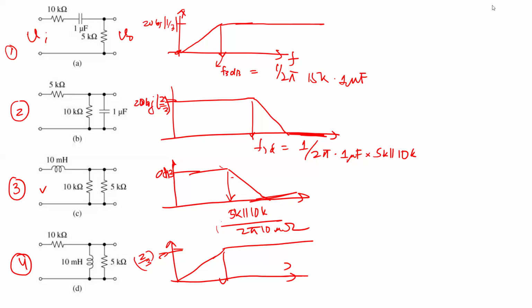If you want to go to microhenries, then you buy those elements which look like resistors, but they are wire wound. Okay. So this is just showing that you can use an inductor to do a low pass filter. For example, this one, you can see it's turned off at high frequency, and at low frequency it is basically a short.